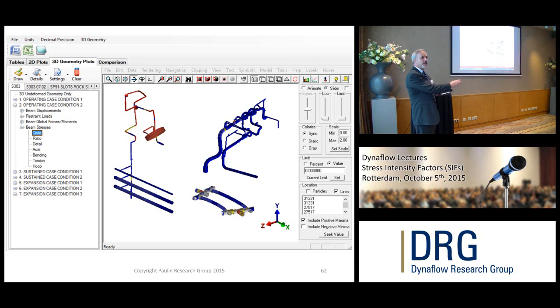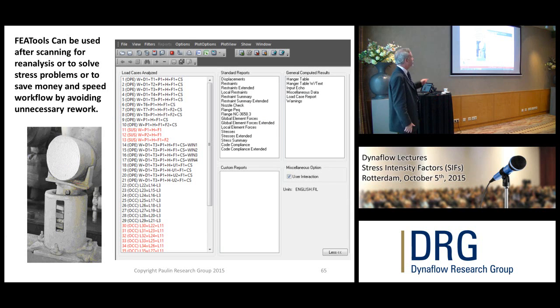What makes it able for you to run a whole lot of calculations real quickly also lets you do a lot of new design quickly. So the hope is that all of this stuff together will improve what you do with pipe stress. Okay, these are just charts and plots. And of course the other thing is FEA tools also help you when you've got overstress conditions, because you're including proper flexibilities, and most of the SIFs that you put in are going to be lower rather than higher. And so you won't see as much red just by default.